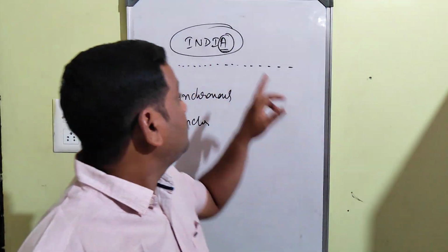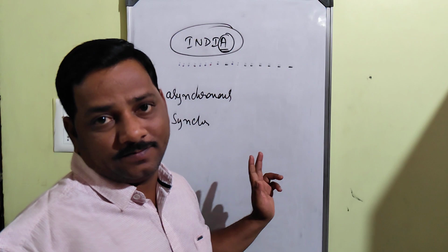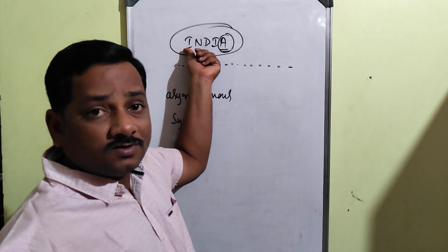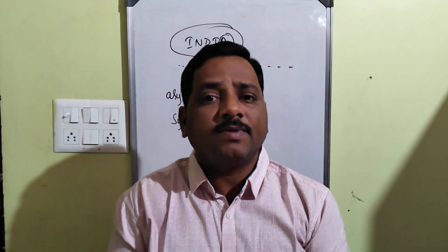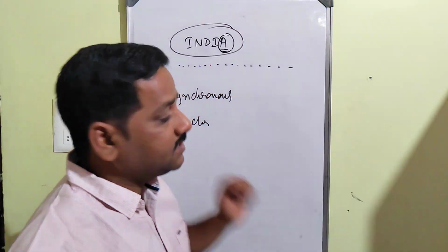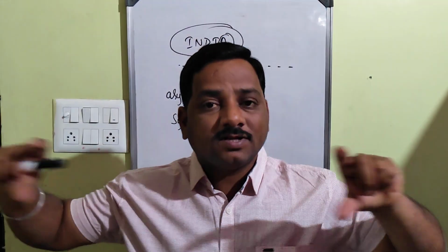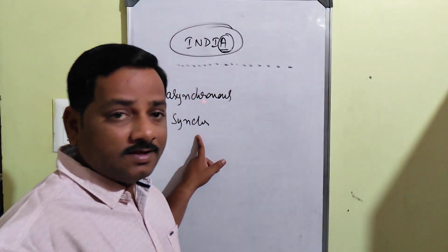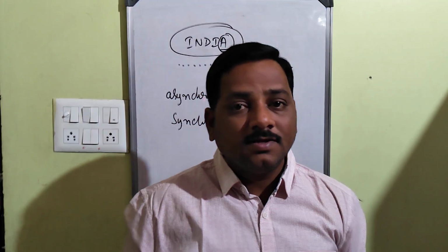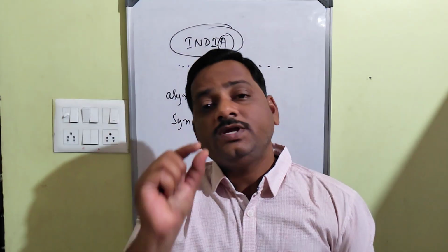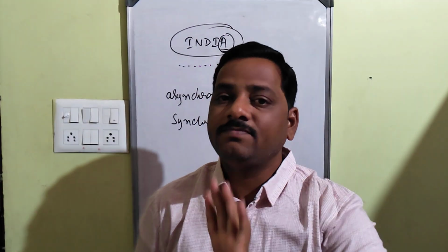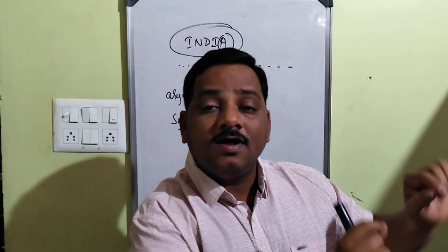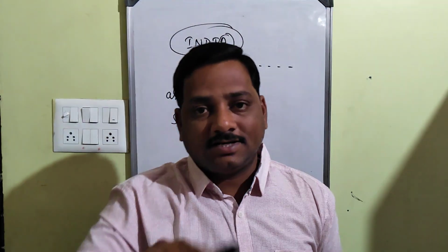We are synchronizing all the bits, all the characters together. So we are taking 8 bits of this, 8 bits of this, 8 bits of this, 8 bits of all the remaining characters, and combining them. For example, we have 5 characters. Totally we get 40 bits. All 40 bits will be arranged in a frame and transferred one by one. That is called the synchronous method. If not, asynchronous means from this 5-letter word, we consider one 8-bit data at a time. 1 byte A will be taken in a frame and those 8 bits will be transferred. After that only we will go for the second character.